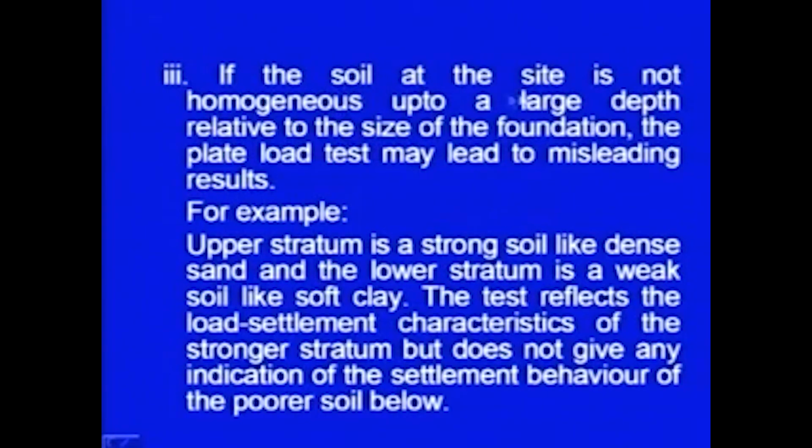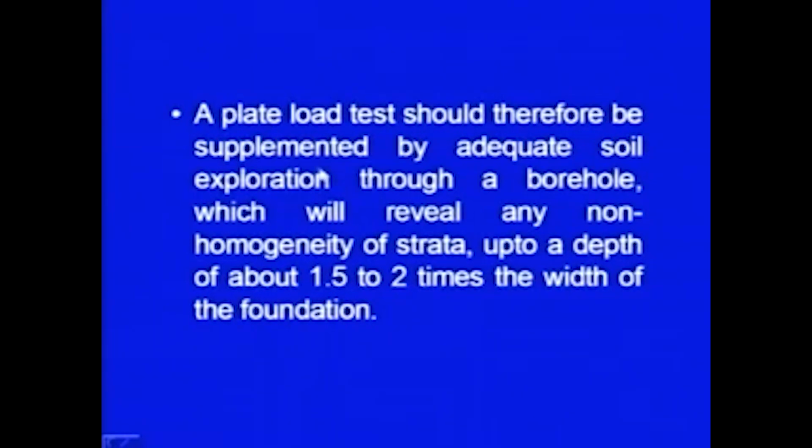So, if the soil is not homogeneous, if the characteristics are different, then you are getting the characteristics of the soil for only a very small depth, whereas in case of the actual foundation, the pressure bulb of the foundation will go much deeper. So, it may give you misleading results. A plate load test should therefore be supplemented by adequate soil exploration through a borehole.